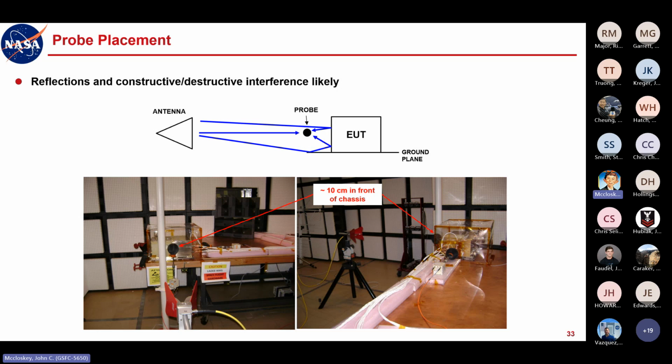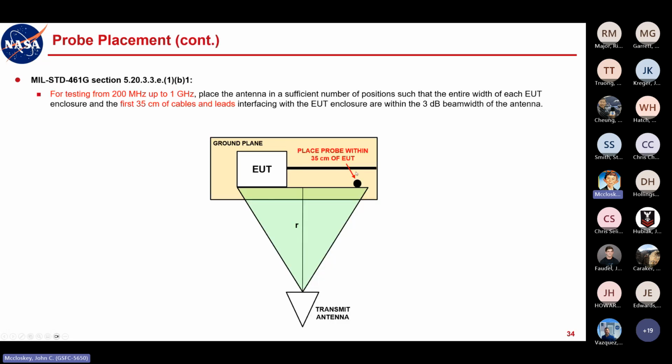It's like a temperature sensor that's right on your engine in your car might tell you it's 140 degrees because that's how hot your engine is. That doesn't mean it's 140 degrees outside. So you have to be very careful about where you put the field probe, and this is not optimal. So we learned that in a test about 10 or 12 years ago.